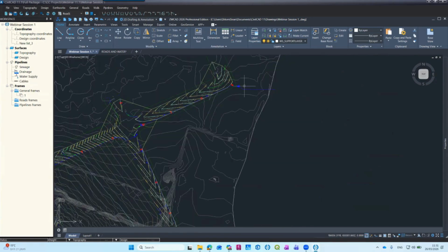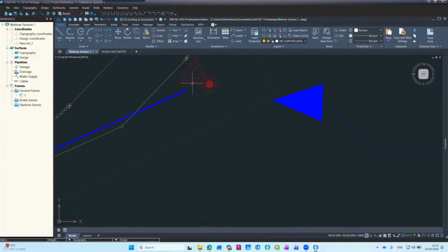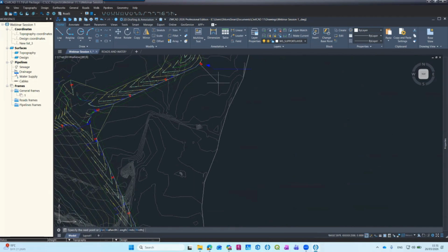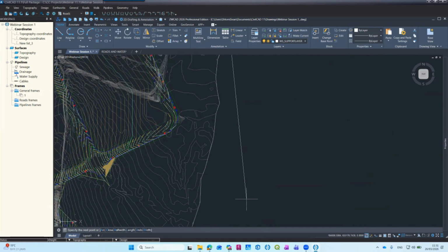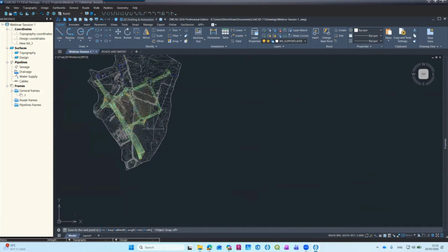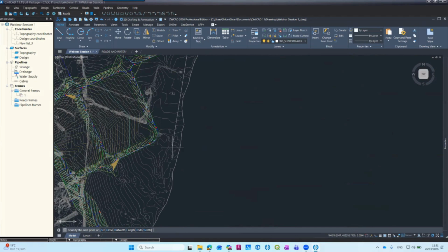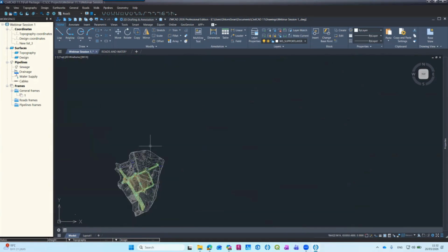And I will start. So I'm doing a polyline from here. Just use my object snap endpoint from here. I'm connecting, going to here. I will move the object snap, and I want to go down south. So here to here, and from here, connect it somewhere.